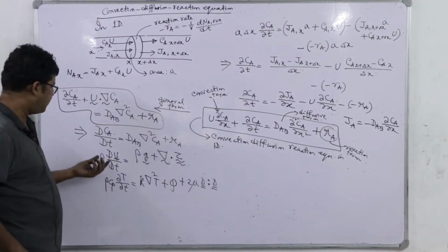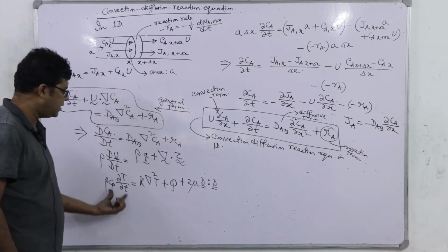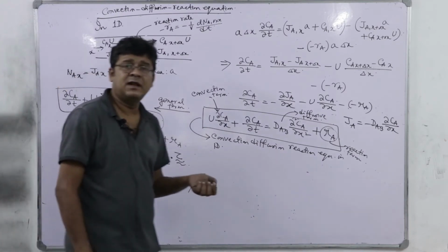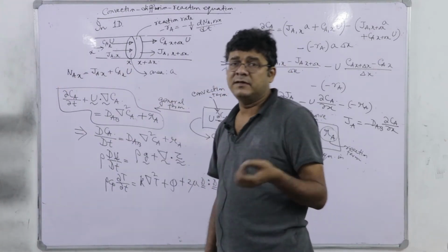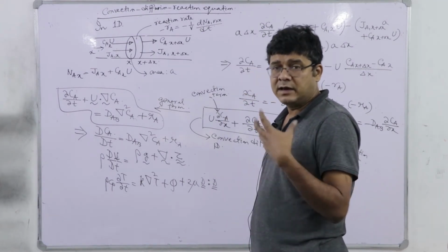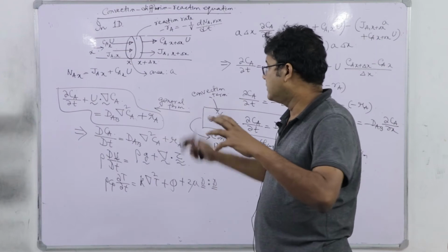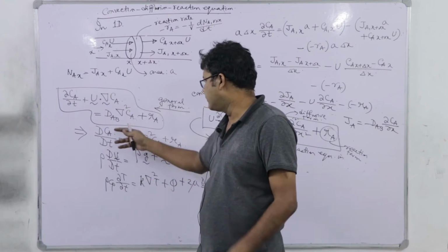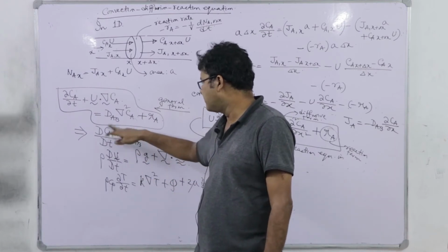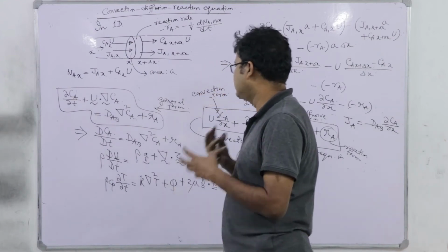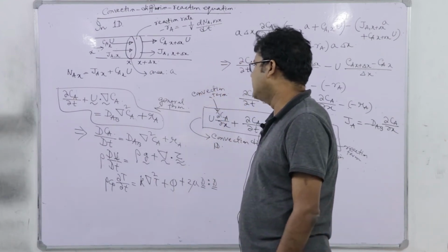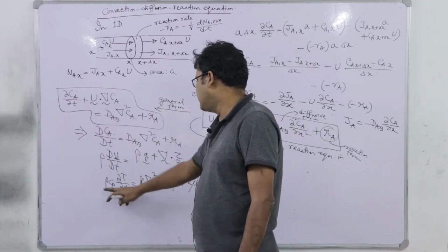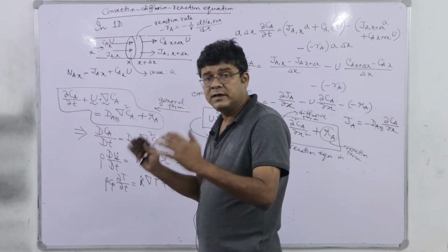Now, you see on the left hand side we have the rate of change of the momentum here, the concentration here, and the thermal energy here, for a particle, because the material derivative means it is a Lagrangian derivative and it represents the rate of change of that property in that particle. Here it is the concentration, some property of the particle. Here we have the momentum, and rho Cp (T minus T reference) is the energy.